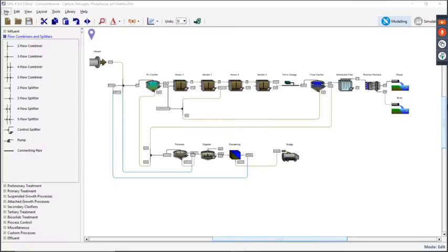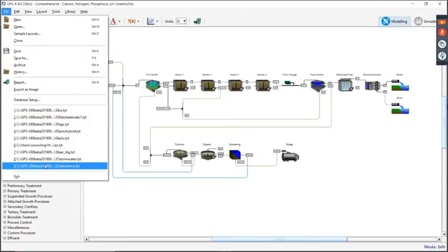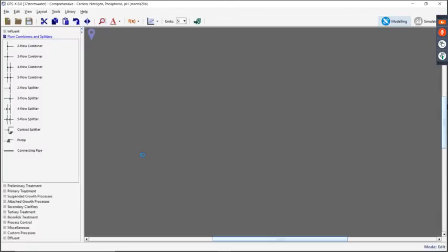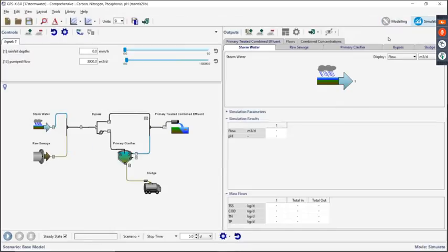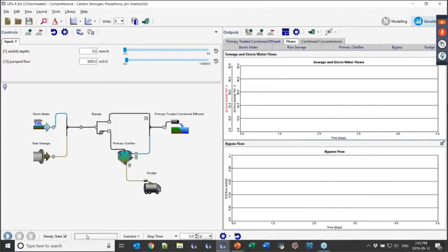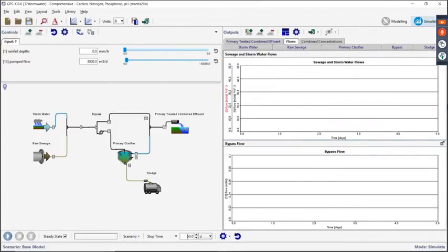The idea is that we can then mix that with the regular wastewater flow, and see the typical behavior you would get when you have a wet weather event that dilutes the flow coming into the plant. In this layout, we don't have the whole wastewater plant. We really just have the influent part, the regular raw sewage coming in, and our stormwater. I'm going to show you the flow rate here, and I'm going to run a long simulation because otherwise it's going to go by too fast. And I'm going to make a bunch of rain happen here, this rainfall depth.